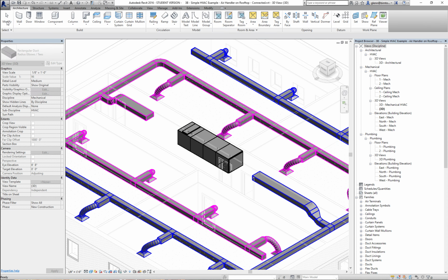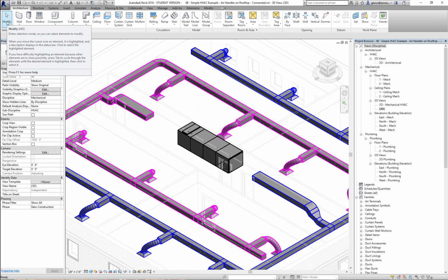So what I'll tend to do instead is think about having a couple of different sections that are very useful for aligning these things. And let's talk about sections that would be useful. When I'm connecting these things, the enemy is being slightly out of plane. Okay, so if you're in plane, you'll get much better connections, it'll line up properly. So if I want to connect these ducts in from the side, a plan view is going to be useful for getting it aligned center front to back.